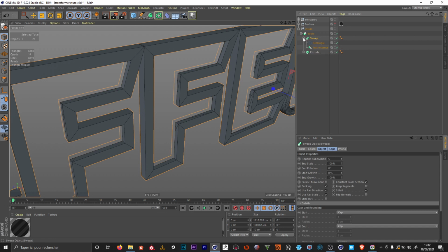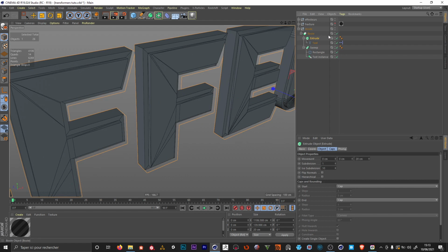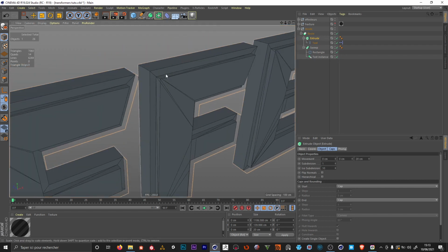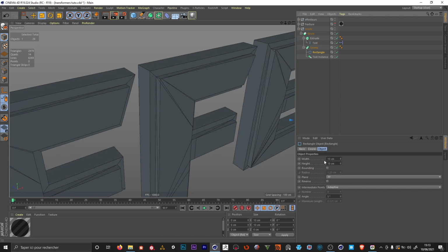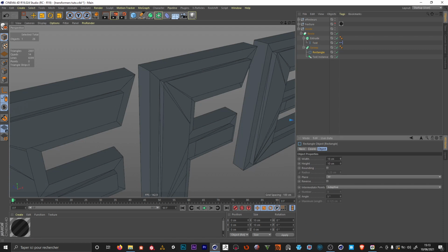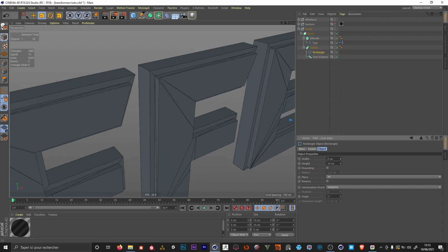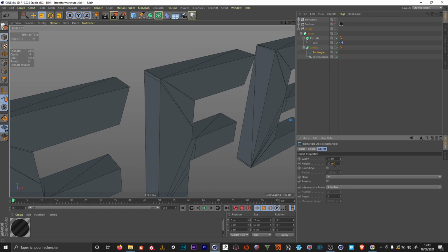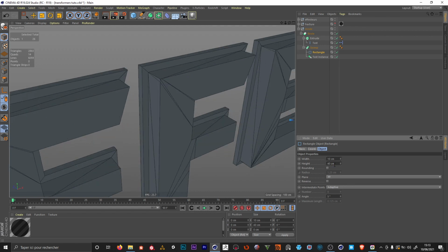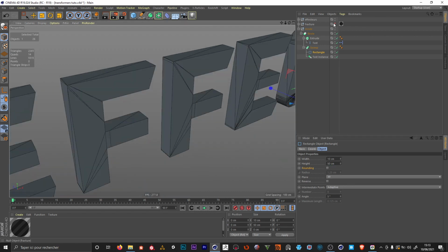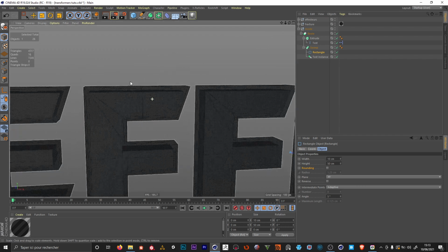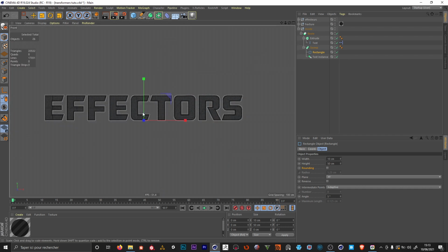In fact, we just want the extrude in the first position. So here we're gonna see the sweep cutting inside the boolean. So I'm gonna select the rectangle, and I'm gonna change its dimensions. I'm gonna leave this to 10 centimeters for now, and I'm gonna increase the height. So here we're gonna be able to erase some part of the text. If I show the fracture again, we have now a nice little inside part for the text.